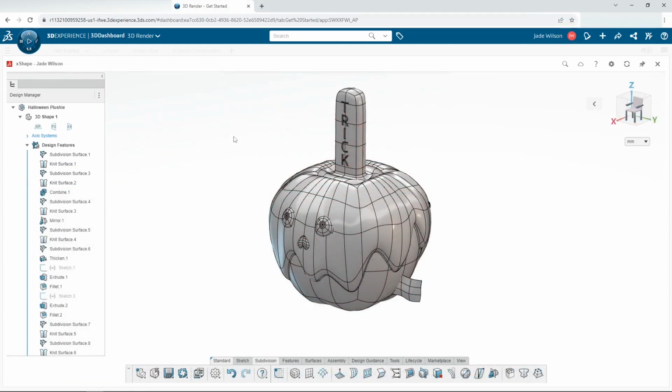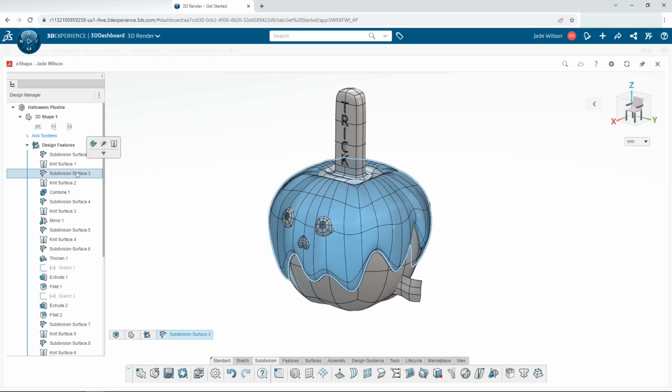When designing in xShape, you really need to start your model with the best primitive shape. This means that you need to have some sort of preconceived idea and choose the shape based on this. For example, I couldn't have started my design with the torus primitive shape. This choice comes with some practice and knowledge of the primitive shapes, so play around with these before starting your design.